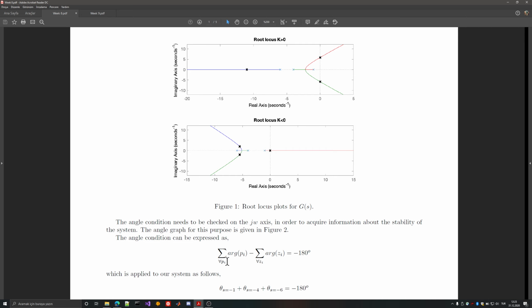The only thing that I have to look for is a sum of 180 degrees for all 3 pole arguments. So basically, I know that this will be contributing 180 degrees here, because we look for the counterclockwise angle, and then there will be a certain angle from here to here and from here to here. So basically I have to sum these 3 angles.